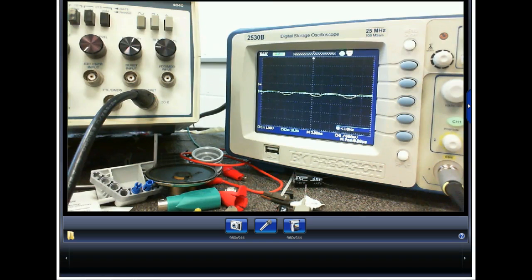Well, what's going on? What do you think's going on? Well, the meter, when we got it on amps, the meter's supposed to have no resistance at all, just very little. It does have resistance. Meter set on amps, and it's set on the 20 milliamp scale, and it's on AC. That's a good point too. That could be wrong. That could be right. So if I had it on DC amps, it's going to show 0, right? You understand that? Because I'm in an AC circuit.